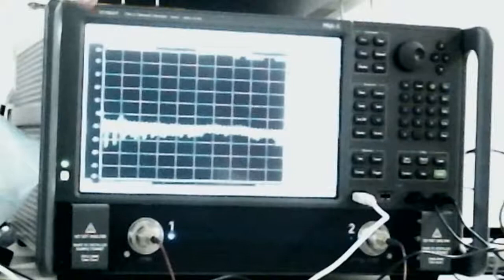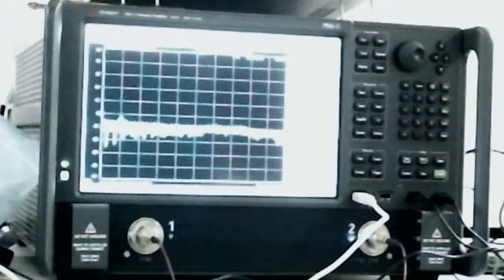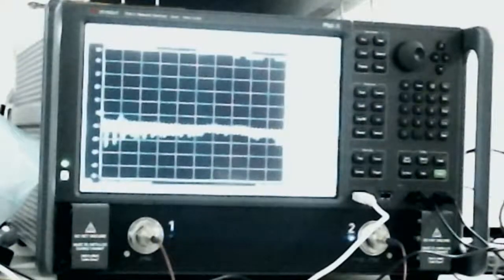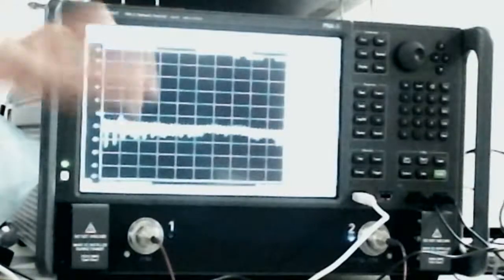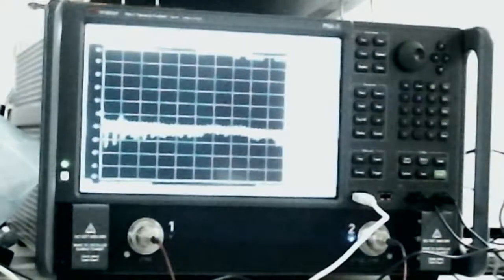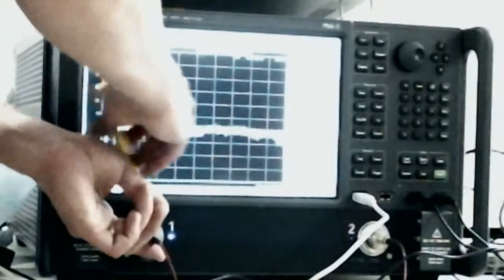Yeah, so I'll show you. P out or P in, for example. Correct. So that's where a source power calibration would be good, because if you want to know what the P1 dB is, you want to know what it is at the device, not what it is at the test port, right? So let's do a very simple case with that. Again, the cal is not going to be very good, but we can go through that, right? So can you show us the power calibration? Yes, I'm going to guide you through that whole calibration process.